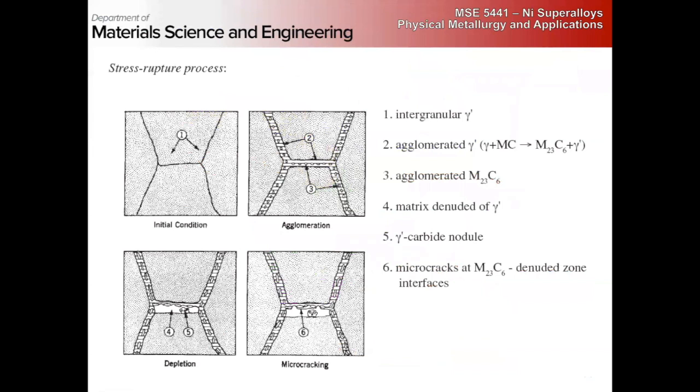So the big danger, the ultimate failure with creep, is the rupture process. Actually of interest, if you think about a disk, it's not going to have to creep all the way to failure for really bad things to happen, right? Think about the inside of a turbine.